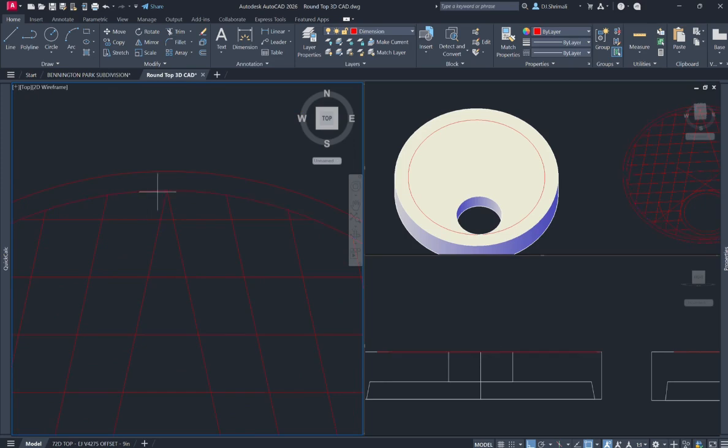So yeah, now we are focusing on the circumferential wire. It's a wire mesh that you wrap around, so it's gonna be a straight mesh, right? So it's gonna have a joint, or an overlap, as you see. It's usually an 8-inch overlap. So here I am creating that overlap to show how the mesh is gonna look like. Okay, so it's just one flat wire mesh that you wrap around. So yeah, you see that.